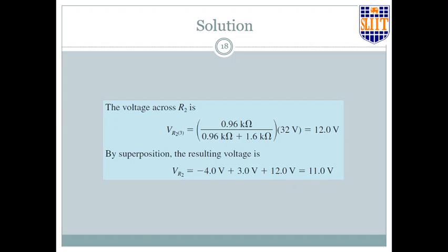You can use the superposition theorem instead of using circuit analysis techniques like the branch current analysis, mesh analysis and the nodal analysis, which consist of simultaneous linear equation solving, but in the superposition theorem you don't have to do that. You consider a source by source, as one source at a time, and the theorem says that the total effect will be the addition of each case, algebraic addition of each case.